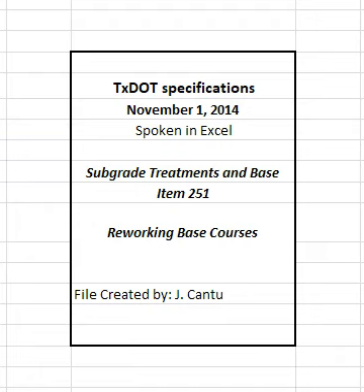4.2.3 Relaying. Prepare subgrade as shown on the plans or as directed before relaying salvaged material. Proof roll in accordance with Item 216, proof rolling, when shown on the plans. Correct soft spots as directed. Return and rework salvaged base material, with or without additional new base material, on the prepared roadbed.